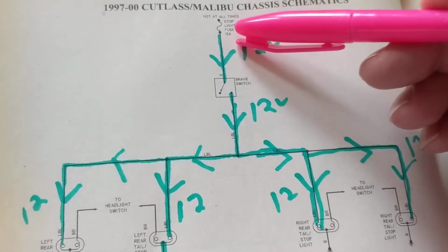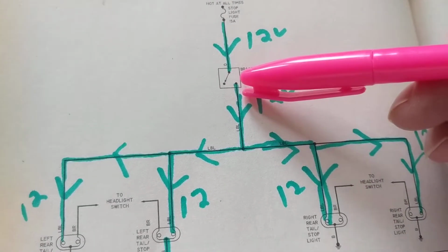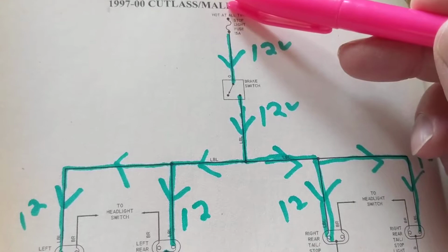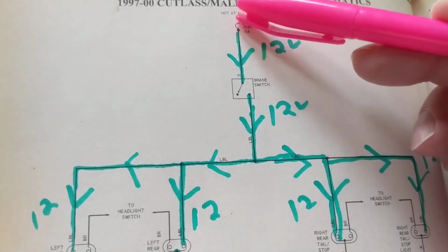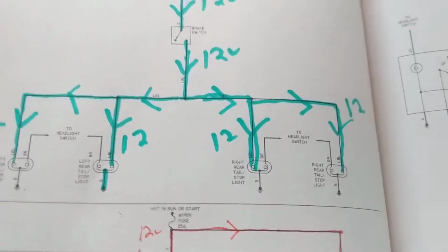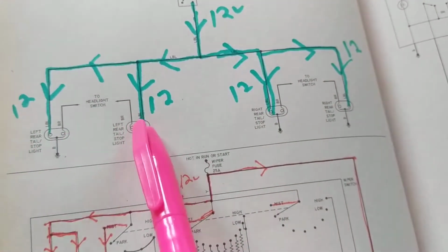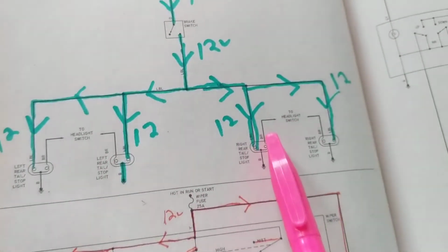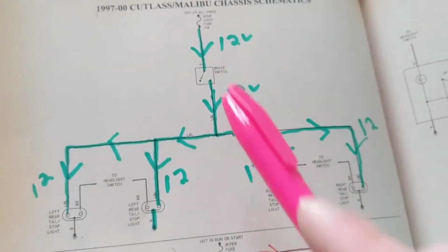If I measure 12 volts over here and I measure 0 volts at the other side, this is open, right? If I measure 12 volts over here and I measure 0 over here, that means there's no connection to the supply, this is open. If all of them are not lit, there's no reason to take out every connector and try to measure 12 volts, because there is no 12 volts. There's no current flowing. So you know what's common to all this.